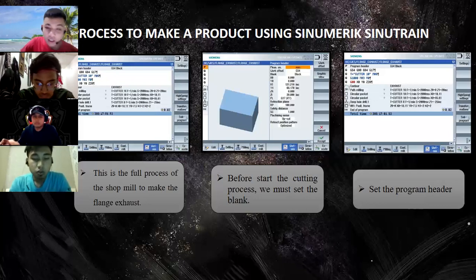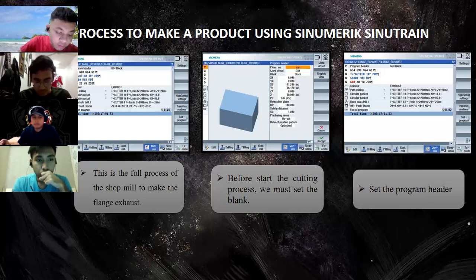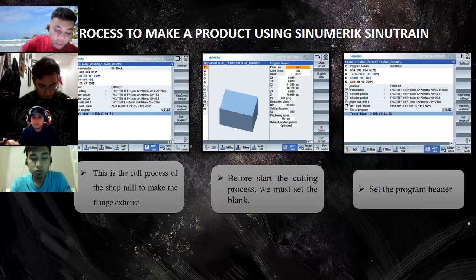After that, the process to make the pocket has two parts, one on the left and one on the right side. To make a pocket, click the milling and then click the pocket button. We choose a tool diameter of size 10 for the tool. For the machine, we choose a centric and single position. The distance for X0 is 18.11 mm, and the distance for Y0 is